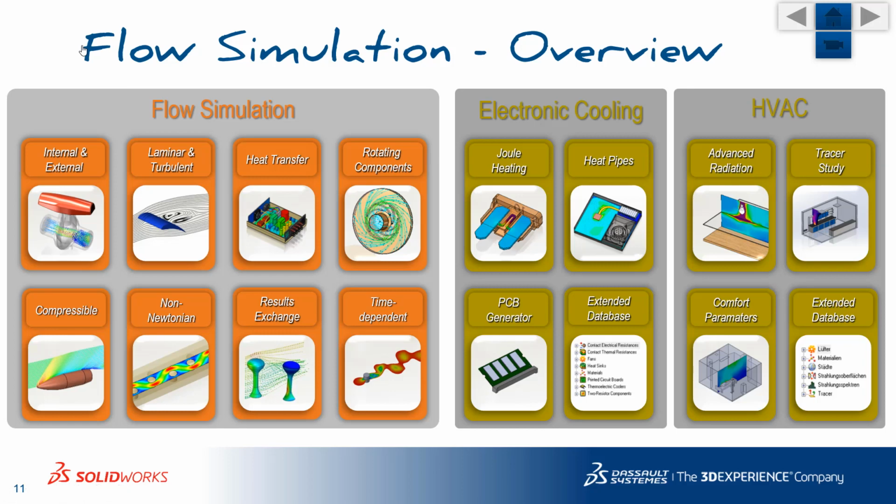Flow simulation is essentially everything that a lot of people will need to do. Internal and external studies, flowing through things, pipes or valves, or around things, external flow. You then have both laminar and turbulent flow. You can talk about heat transfer, how much heat is transferred from this solid, this chip, to the air, and how is a fan affecting the heat transfer of my electronics cooling box or a server rack or this room.